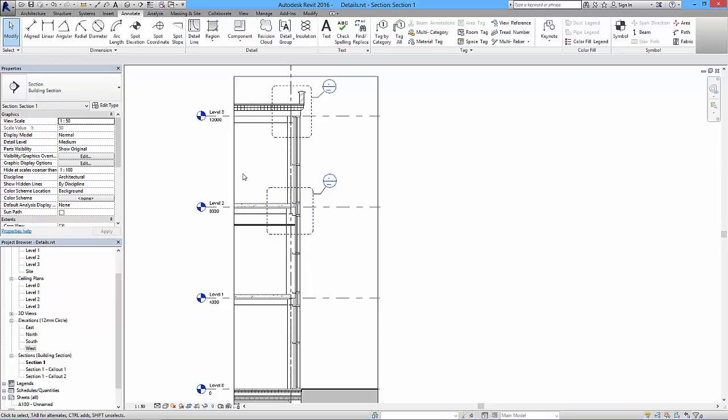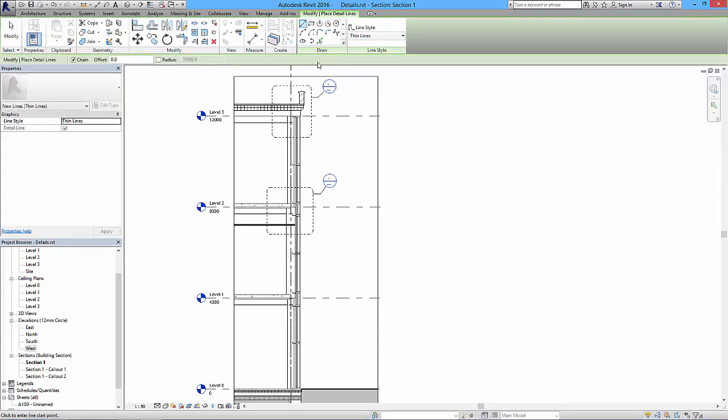It's only the general modeling stuff that we would actually see in cut form. A lot of stuff in Revit, contrary to popular belief, is drawn in 2D, and it's all drawn from this quite simple little panel. So you've got the detail lines, which are again this sketch-based system, and we've got these types of lines that we can play around with.